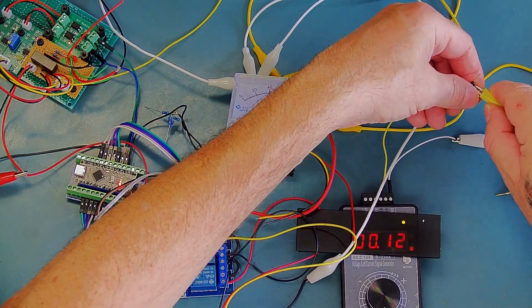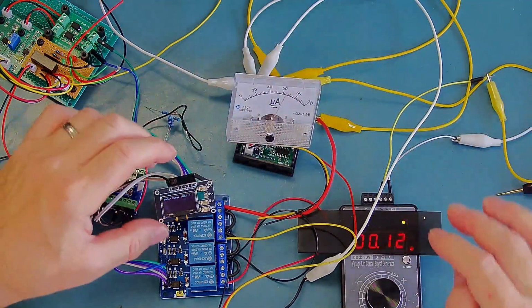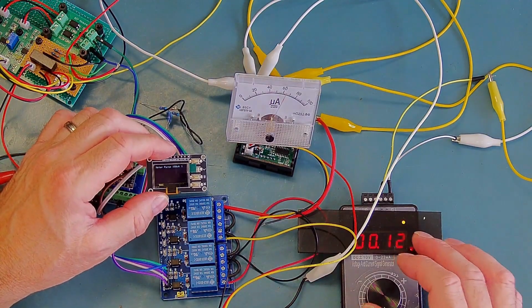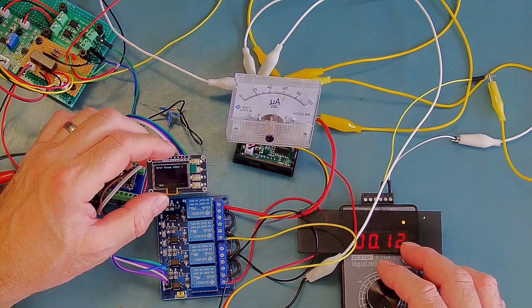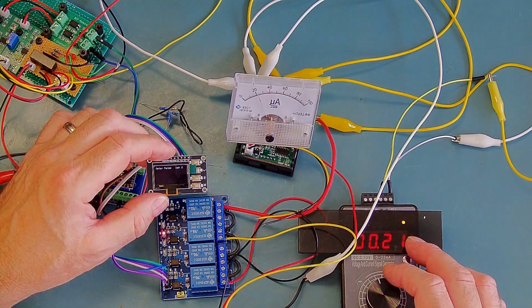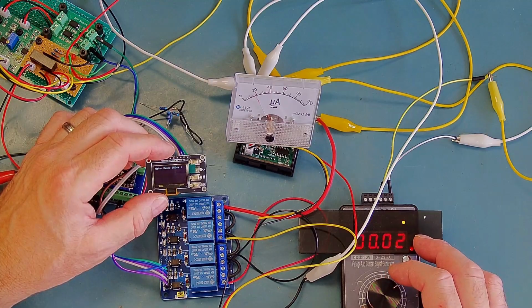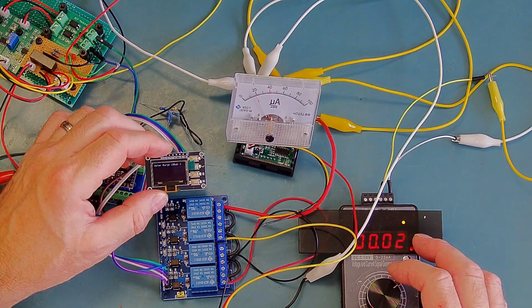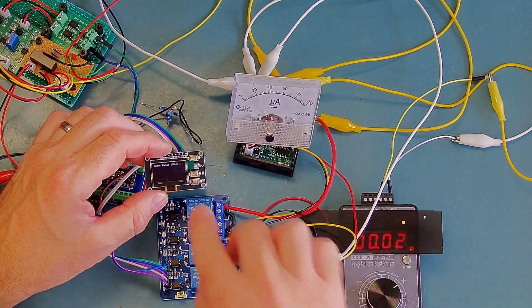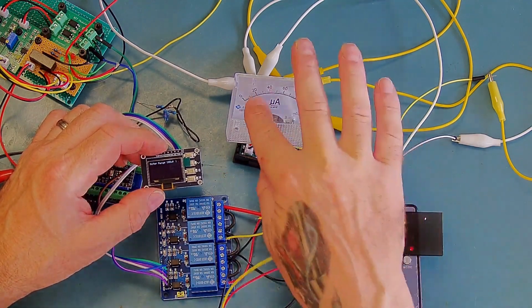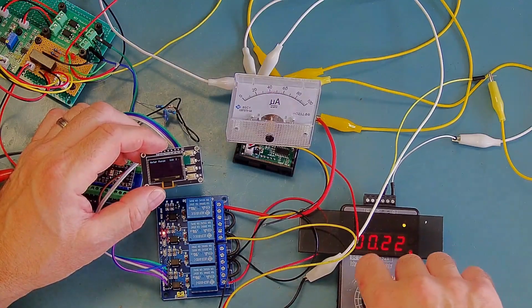Now I've demonstrated the fact that this meter on here isn't accurate, I can take the digital meter out of circuit. Okay. So now we can crank up. Okay, so let's just do that again. So I'm going down range. Okay, so we've gone down below the 1 milliamp range. We're now onto the 100 microamp range. We've got it saying about 0.2 thereabouts.